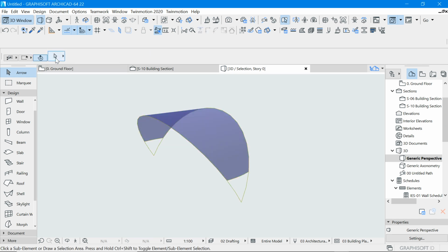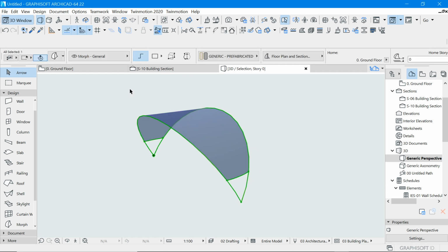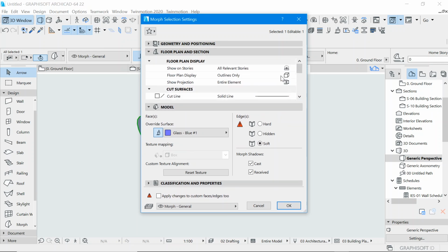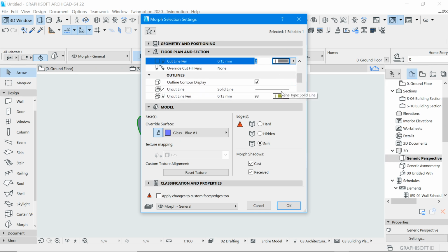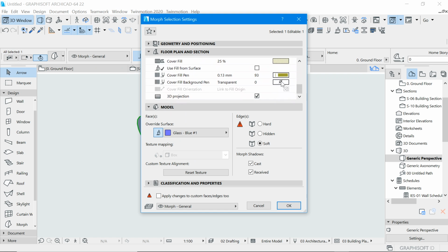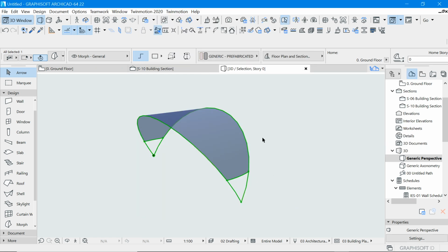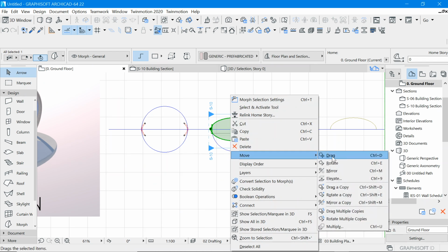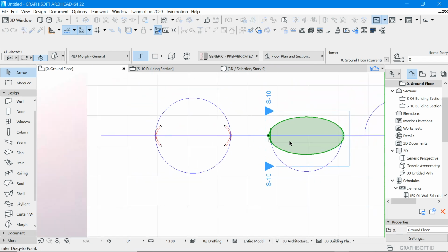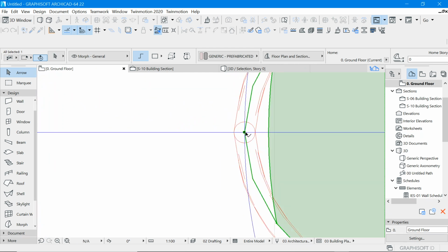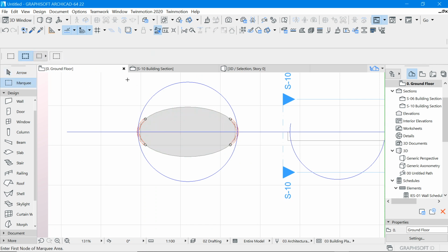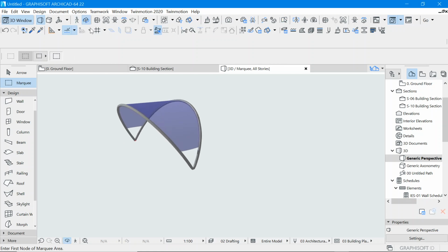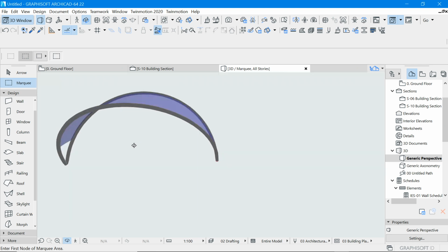Then I now get out of the edit mode. So everything is selected. I go back, make that a little bit smooth. Floor view, change this color to a light black. Make all these changes. Then it's okay. So once I have this, go back on ground, copy that same, drag that same element into the other one we have just created, and then if we again go 3D, we find that we've just created a certain portion of our gazebo.